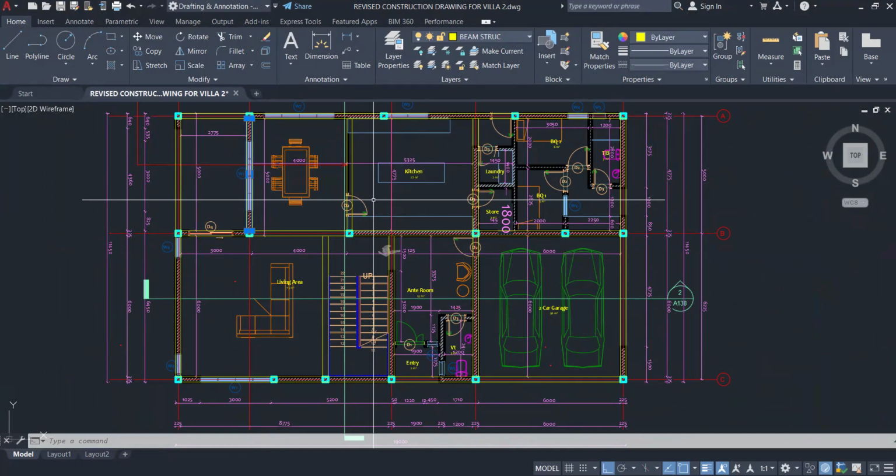I don't understand you. Your beam is 250 by 450. Your slab is 150. So for it to not show, that is why we are placing it on top of the wall. But now in the living room, there's no wall there. And we have to divide that panel. If your client has money now, you can make this panel 150, 175, and just leave it like that. But you know the economy nowadays, so it will be difficult.